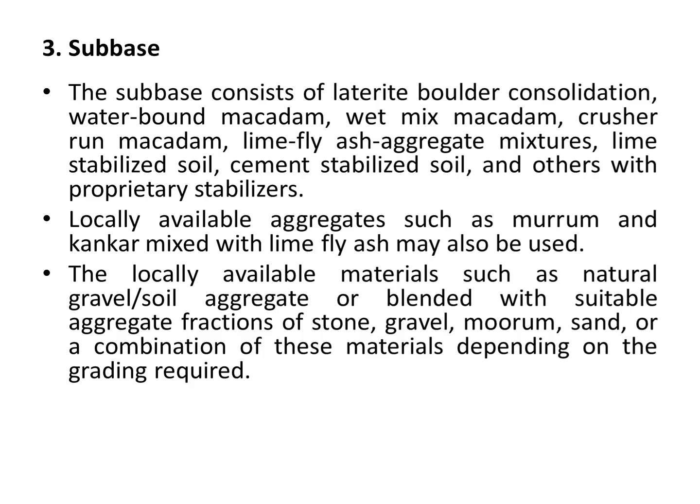Locally available aggregates such as moram and kankar mixed with lime fly ash can also be used. Locally available materials such as natural gravel and soil aggregate are blended with suitable aggregate fractions of stone, gravel, moram, sand or a combination of these materials, depending upon the grading required.